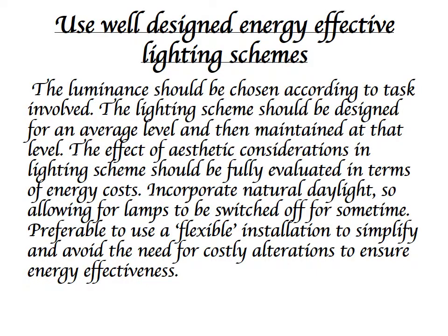Use well-designed energy-effective lighting schemes. The luminance should be chosen according to the task involved. The lighting scheme should be designed for an average level and then maintained at that level. The effect of aesthetic consideration in lighting schemes should be fully evaluated in terms of energy cost. Incorporate natural daylight, allowing for lamps to be switched off for some times. It is preferable to use a flexible installation to simplify and avoid the need for costly alteration, to ensure energy effectiveness.